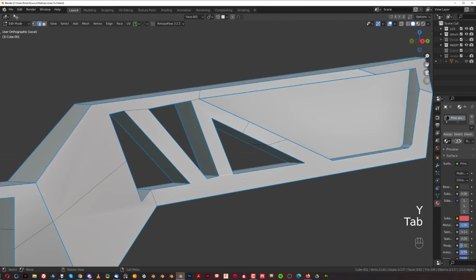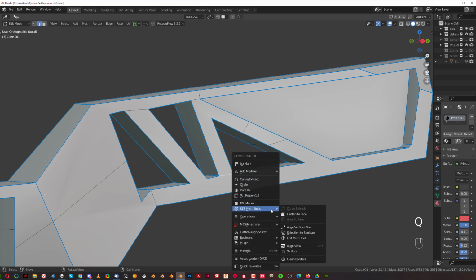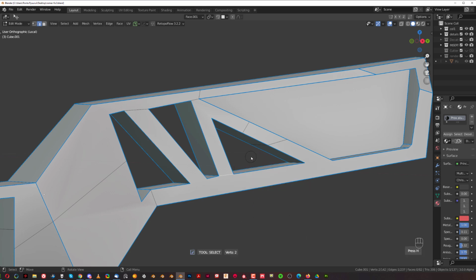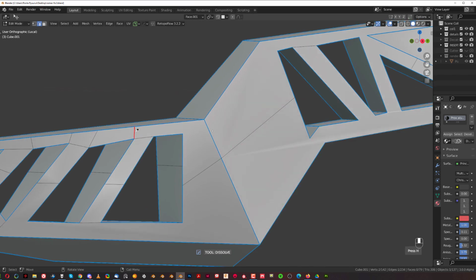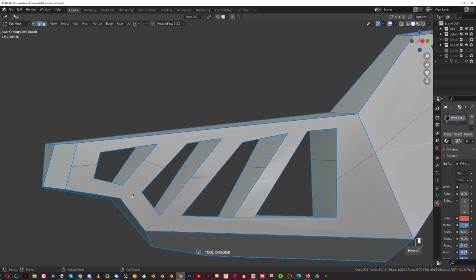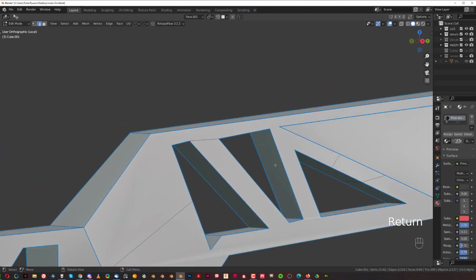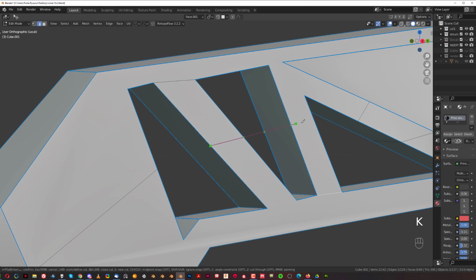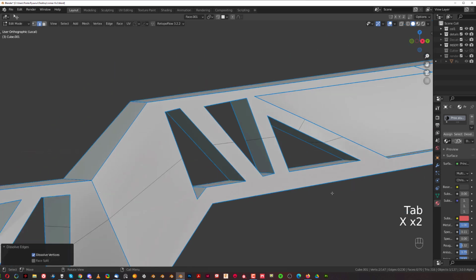Cool. Let's remove these. What we can do is go to edit mesh tools and press J. Not J, sorry. D, I think. And we can delete edges by clicking on them. It's very convenient. Can't delete this one for some reason. Interesting. I'm gonna deal with it later. So delete all these, and at the end you need to press enter to approve. What's going on here? Why cannot? Because there's no knife going through here, right? So do this and then remove that garbage, right?